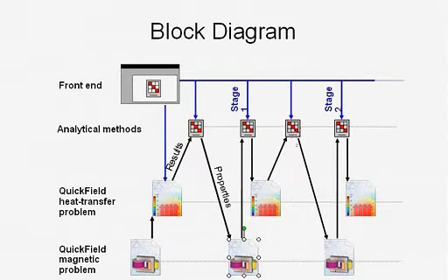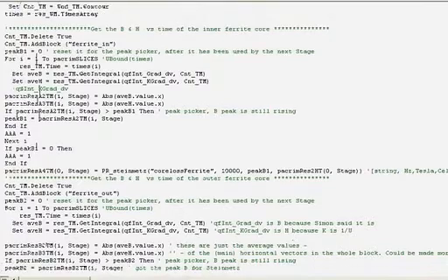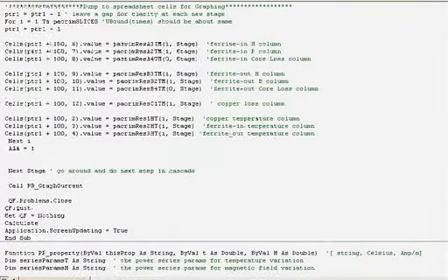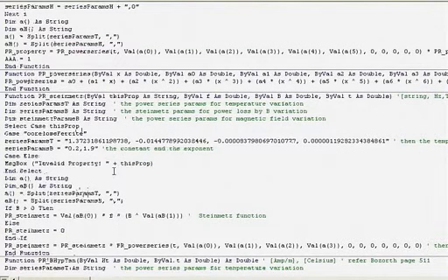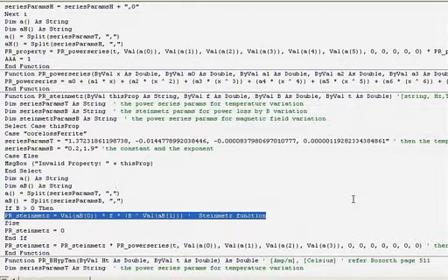And I'll try to highlight the core piece of, there it is. I'm highlighting the actual Steinmetz function now, which is a constant times the frequency times the flux density to an exponent, and the exponent happens to be 1.9.